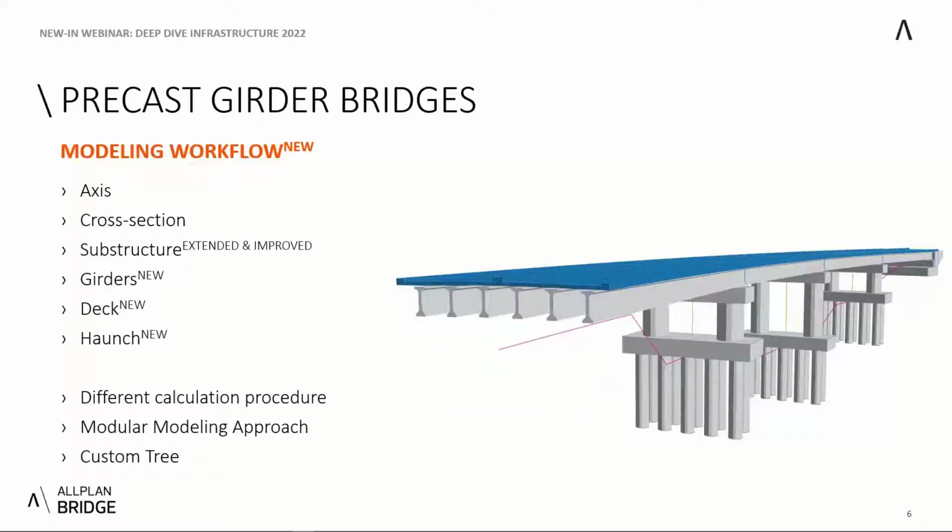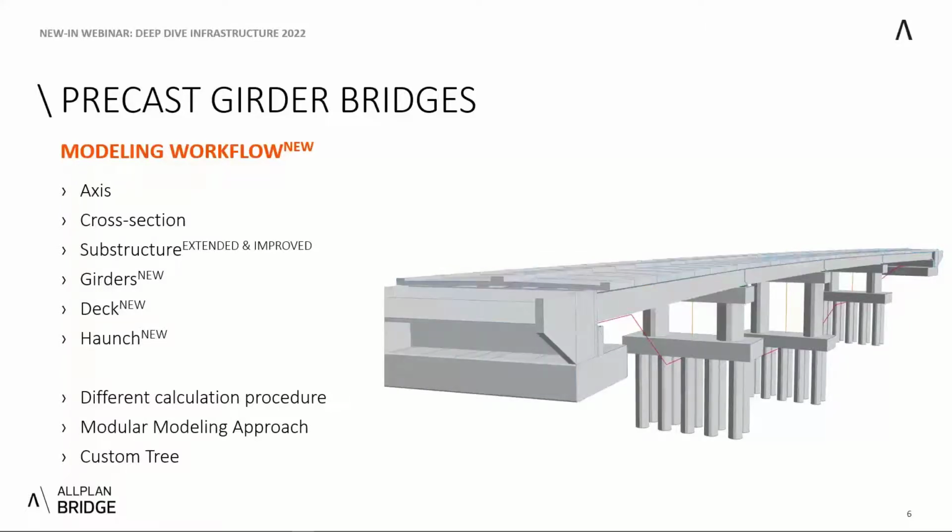And at this point, we have generated 2 bridge elements with 2 different approaches, and hereby a gap is generated. We all know it by the name of a haunch or fillet, and its 3D geometry is highly arbitrary. In Allplan Bridge, we have found a very simple solution for the modeling of the haunch, and for this we use the 3D Boolean operations. This concludes the modeling, and the model can be finalized.